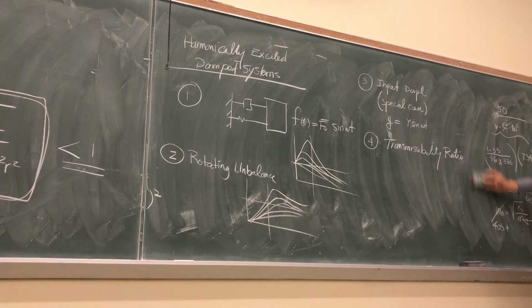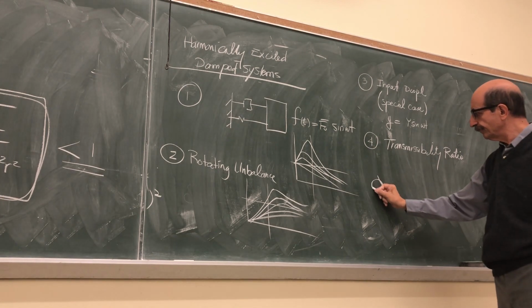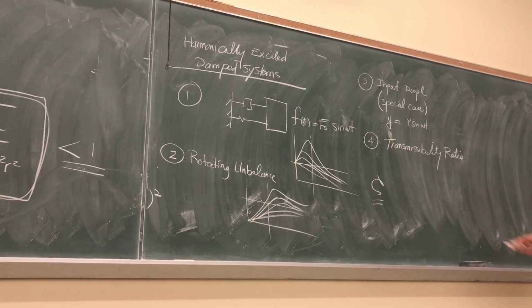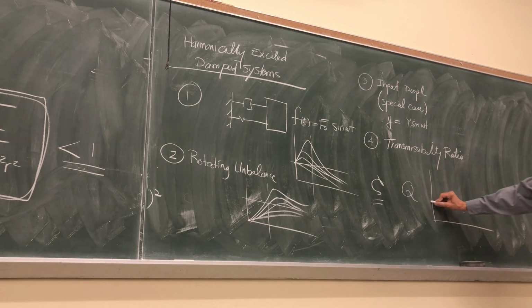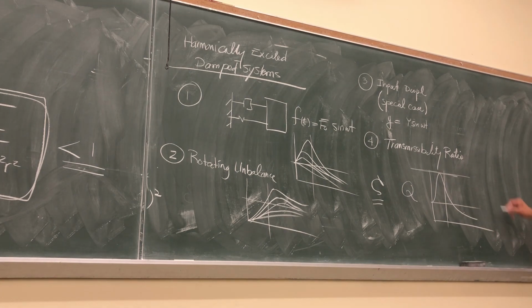One of the topics we studied in between was the evaluation of damping, okay? I'm not sure if we're going to consider topic 5 or whatever. We introduced the concept of Q, that basically, given the frequency response function, if you can plot that and find the maximum value of this frequency response function, this is almost 1 over 2 zeta, okay?